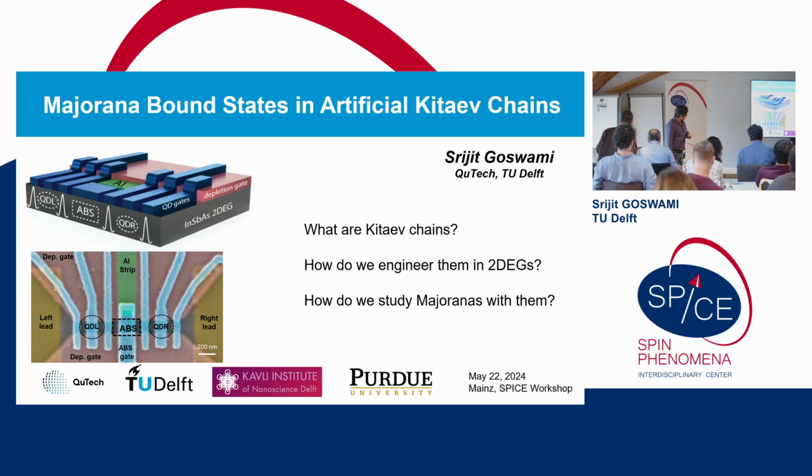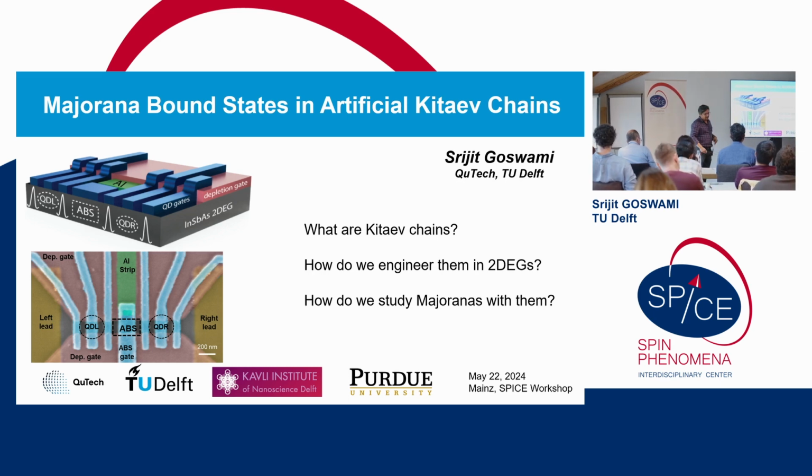So before going further into the talk, I want to talk about the kind of devices that you'll see, the kind of systems we work with. You can see this 3D schematic of a two-dimensional electron gas, and in the spirit of, for example, Alex's talk, we don't work with 50 by 50 arrays. We just work with two quantum dots. You can confine electrons where you want. And I will be talking about systems with two dots.